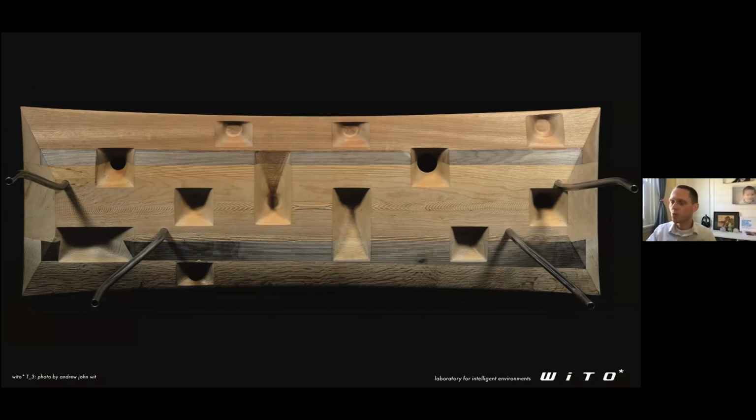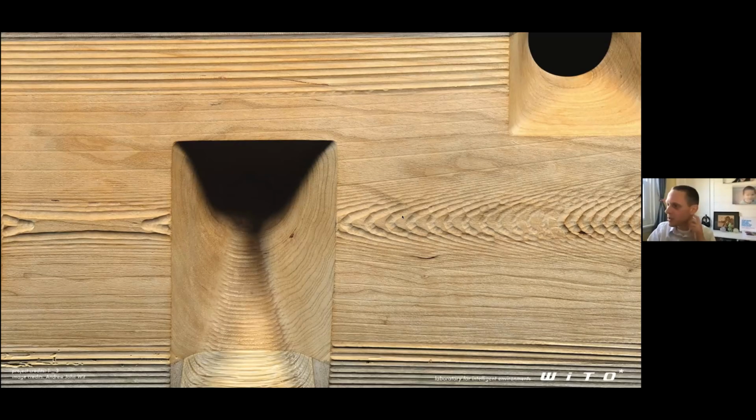So with all of my students, I encourage them not to just use the tools as they're meant to be used, but also to misuse the tools to see what can arise from misusing a given tool. And here you can see some of those details of how this 10,000 pound machine was actually jumping as it was cutting, because the speed was too fast for the radius.